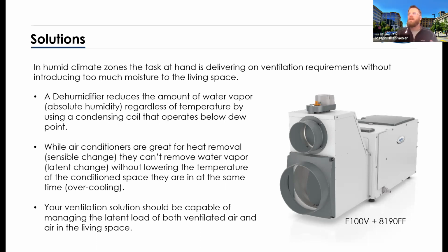And the big takeaway you'll see from this is that a dehumidifier is a dehumidifier and an air conditioner is an air conditioner. So it's not that air conditioners aren't effective. They're effective at doing what they're supposed to do, which is manage temperature. The fact that they reduce some humidity is a great side effect, but it's not what they were designed to do. We take the hot air from them and we blow it back outside. We keep the air in with a dehumidifier. What we're trying to do is simply remove the moisture. That is the only job that a dehumidifier has. And again, it can do it without lowering the temperature of the space.